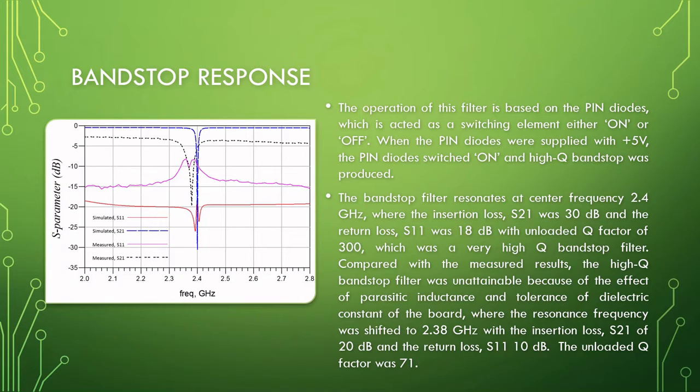Compared with the measurement result, we can see that the filter is shifted to 2.38 GHz with the insertion loss of 20 dB and return loss of 10 dB. The unloaded Q factor was 71.